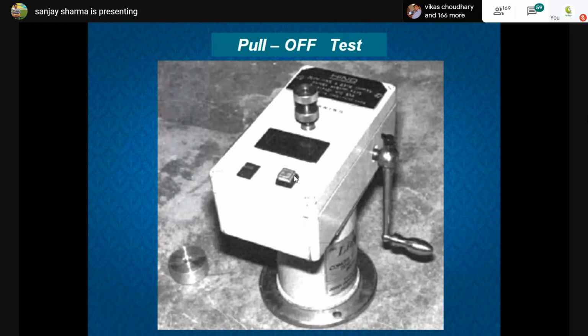We then tested everything using all our systems, and found that yes, the strength was not more than M25. So their engineer suggested strengthening by carbon wrap system, and we used this pull-off test to test the carbon wrap. Even one of the green buildings in Chandigarh, Godrej, which was strengthened by carbon wrap system only, has been tested. There, to check whether the bond between the concrete and the wrap is okay, we used this pull-off test also.